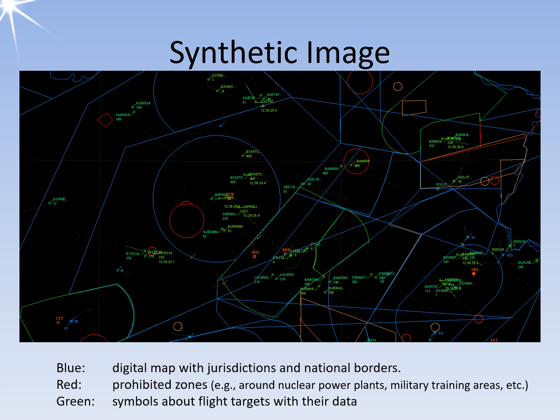A synthetic radar image no longer consists directly of the analog echo signals but of the graphical display of the digitized data with information about this echo signal. The size or strength of this echo signal isn't shown here, but only the information that there is a target with a given course and speed, and its coordinates are completed with additional information from secondary radar.